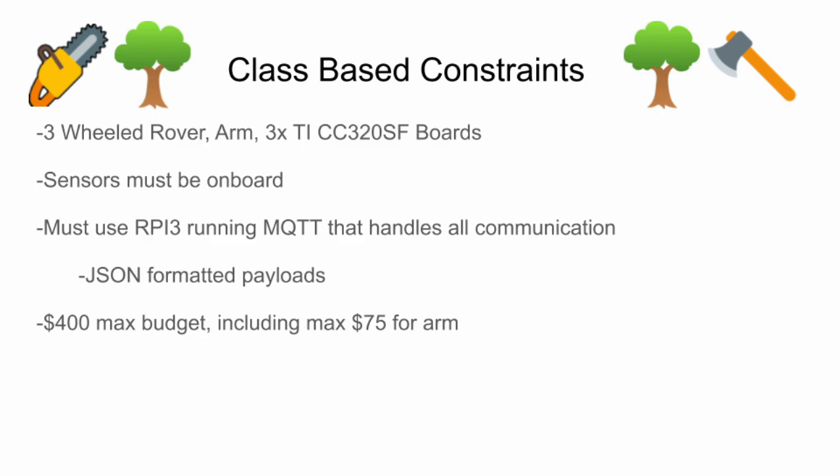An example of an incompatibility would be using an arm that required more than 4 pulse width modulation pins, because the TI boards only had 4 pins that control PWM. So if the arm had, for example, 5 servos that needed to work properly, then it would not work. Another example would be size and power requirements. What would power each component, as using TI boards was not allowed as a power source. Overall, we met all constraints and did not have any issues.